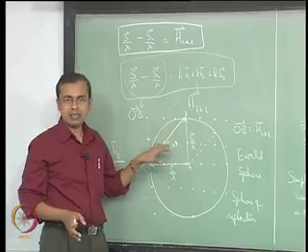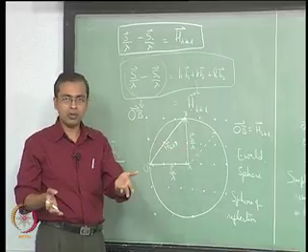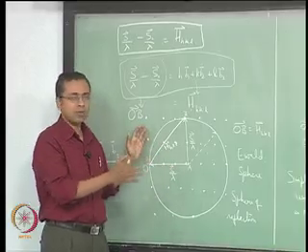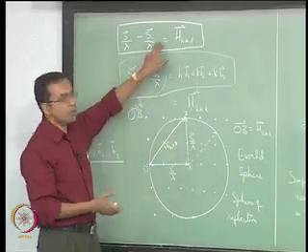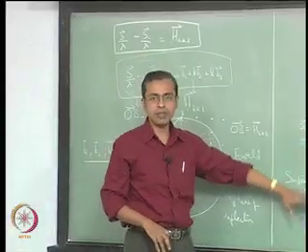The set of points that are there, which are reciprocal lattice points, are based on the material you have chosen, which happens to be simple cubic. Therefore the reciprocal lattice also happens to be simple cubic, and then you see the interaction based on this relationship, you know when diffraction will occur or when it will not occur. Okay, so this is with respect to simple cubic.